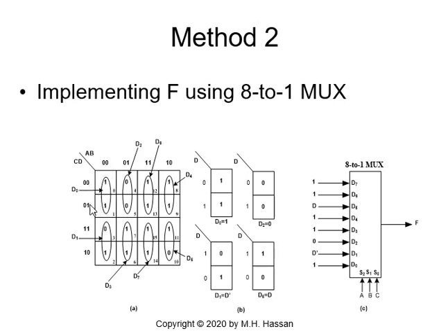And those 2 cells, where C is equal to 0, I will have this tiny map, where it is 1, 1. It is the D0 map, with the variable D. See, it is a D map, because the variable D was not taken since it's not a select line. We are working on a 3 variable map. So once we have the 1, 1, we can circle it, and this will give me D0 equal to 1. We do the same thing here.